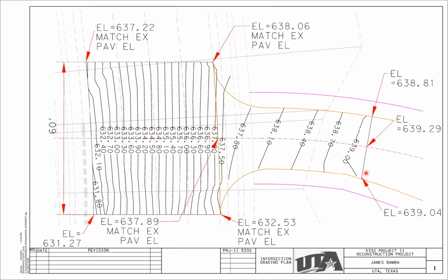So you can see from the contour here, they all have positive impacts. The contour numbers are reducing. So in terms of drainage, I'm having no issue from my road to road 43. Everything is draining from my proposed road to road 43 without having any issue drainage wise.